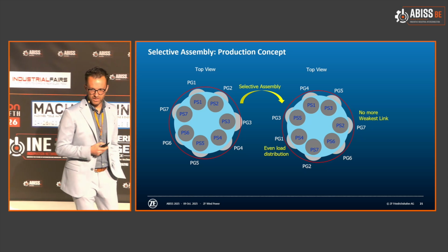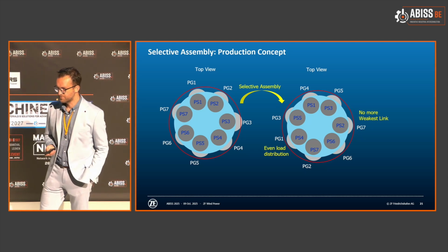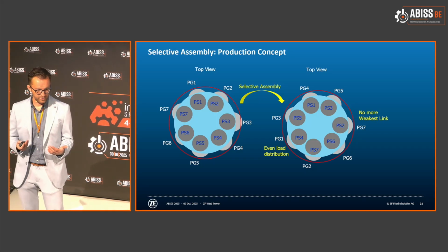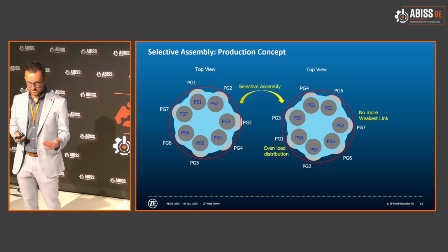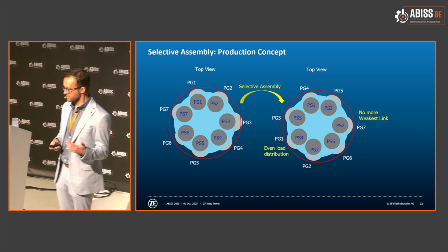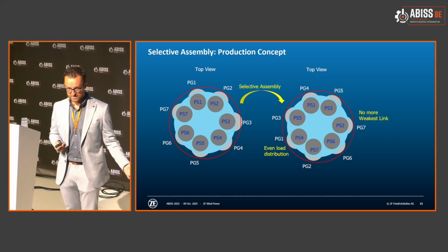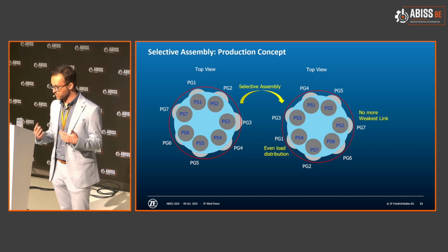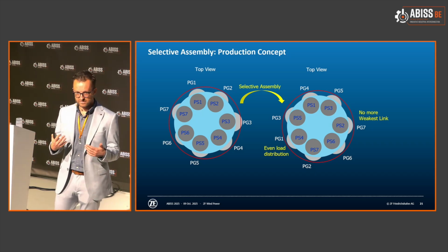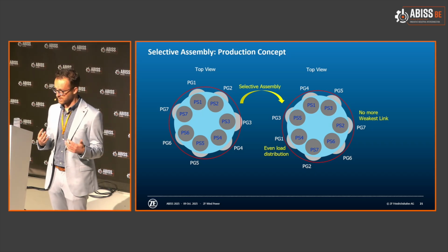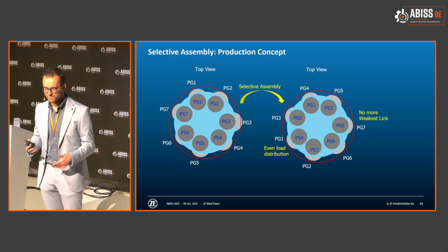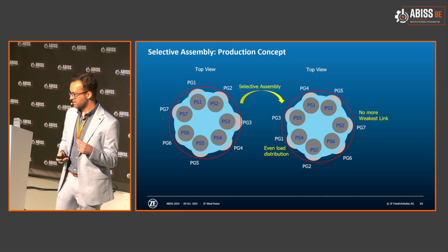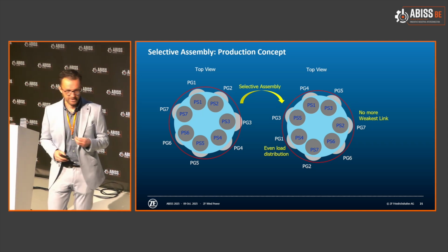Now, how we dealt with this variance introduced by the operator on the left-hand side of the picture was again by introducing safety factors. We designed our gearboxes to handle a certain torque value, and we then subtracted 10% of that, just to be on the safe side, because there is always statistics possible that there is a weakest link. So we always had to assume the worst case scenario. We made sure that we gave them a product which in theory could handle more, but we couldn't sell it as such.